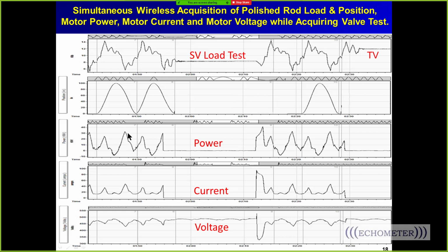That means that the downstroke peak is higher, so we are weight heavy. The weights are too far out, just by looking at the kW. This is the current, and the current doesn't go below zero. The kW does, and where it goes below zero is where the motor is going faster than 1200 RPM, or synchronous speed, and it generates power.